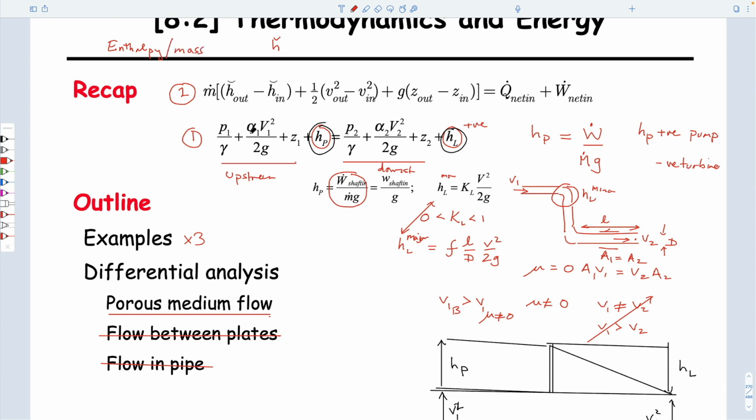So joules per kilogram, or kilojoules per kilogram, is equal to the internal energy plus pressure divided by the density of the fluid. And so we use that. You see that now the pressure is included in this term. So this term includes pressure, velocity, and head. It's kind of Bernoulli, but now it has this extra internal energy term.